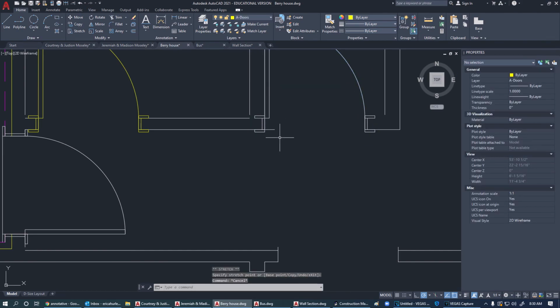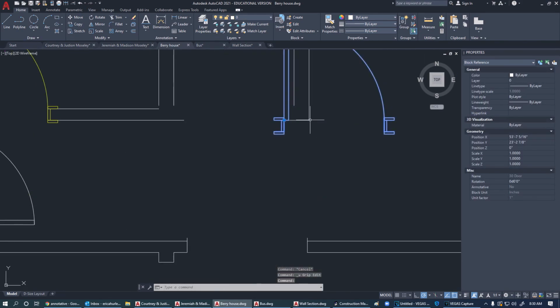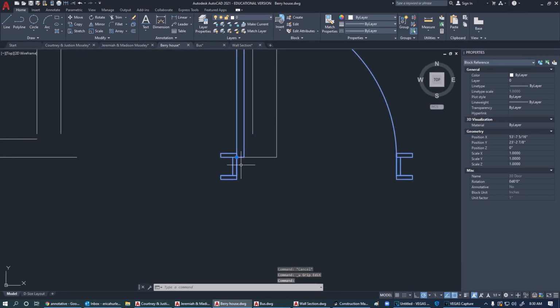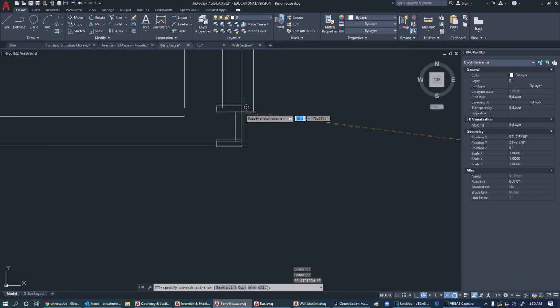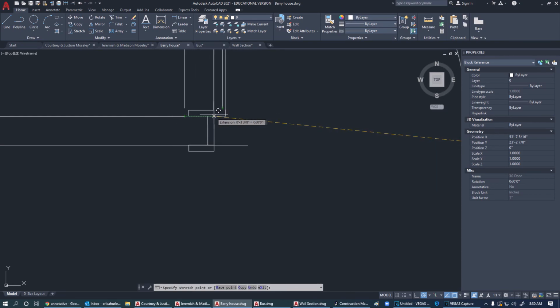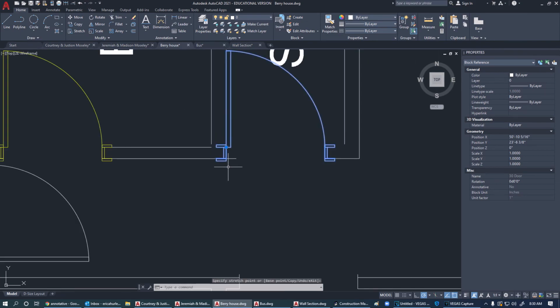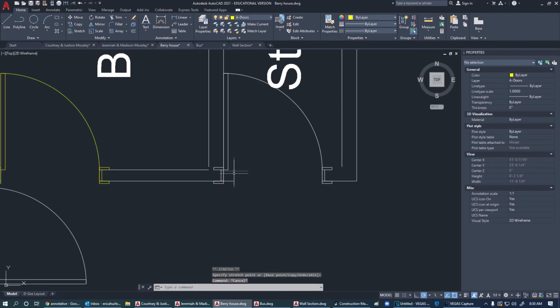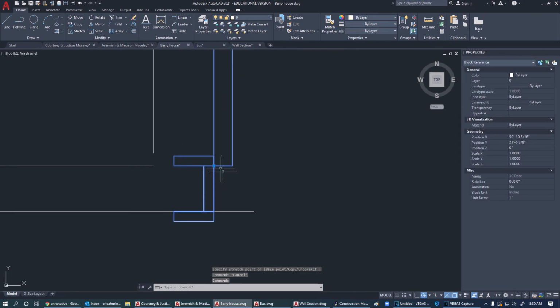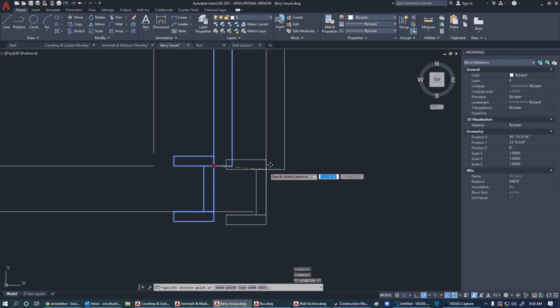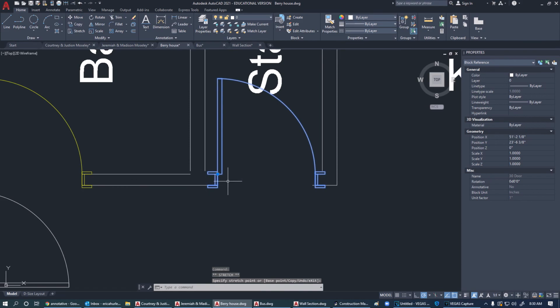Notice what I did there. Let me show you one more time. All right, so I didn't have to hit move or anything. I just grabbed its node there, where the base point was. And I went over here and I just touched on this line, and I touched on that line, and then wherever those two come together, bam, apparent intersection, and then that gives that. Of course, that's in the wrong place, isn't it? It needs to be out here somewhere, doesn't it? Or in the center. I need to figure out where the center is.